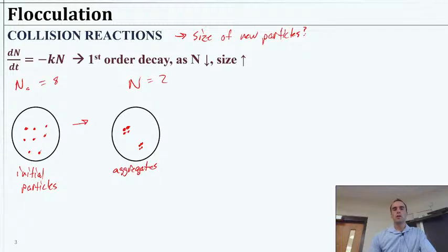Now, of course, you could do a reverse engineering sort of situation and say, well, I know my system can settle this size of a particle, so how long do I need to let them flocculate, or what conditions of flocculation will be sufficient to get it there, right? So whenever we're dealing with one of these problems, we're not necessarily looking at the same exact endpoint each time.